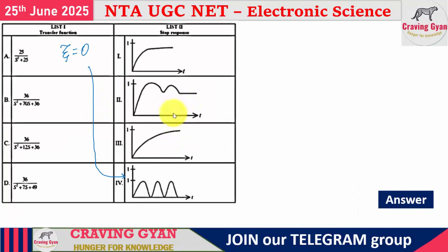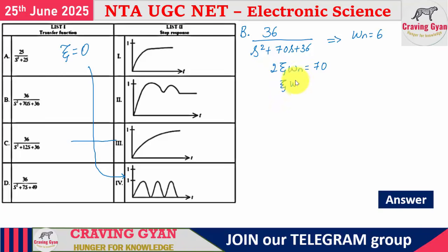Now look at the things. Remaining things we have to solve. 36 divided by S square plus 70S plus 36. B part we are taking. Based on this, we are getting omega n equal to 6 radians per second. 2 zeta omega n equals 70. Zeta omega n equals 35. Now what is the value of zeta you are going to get?